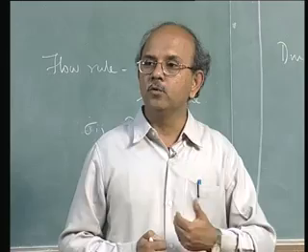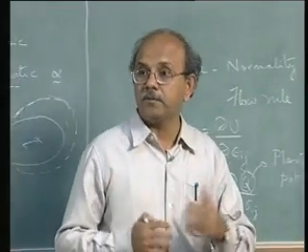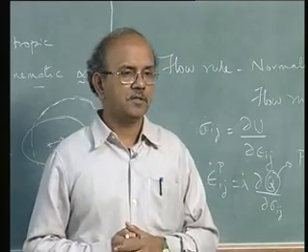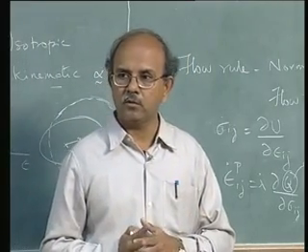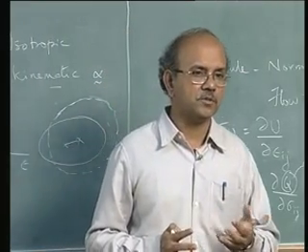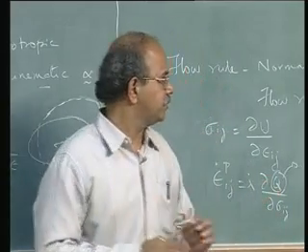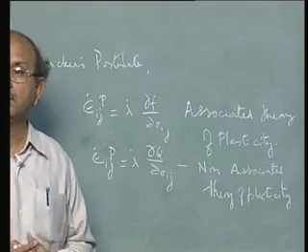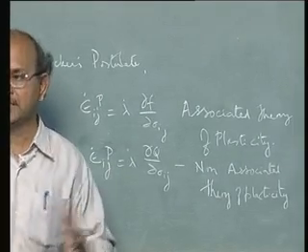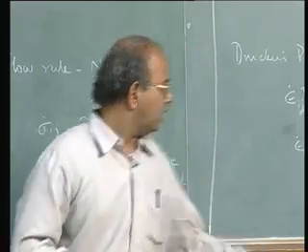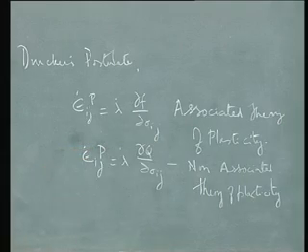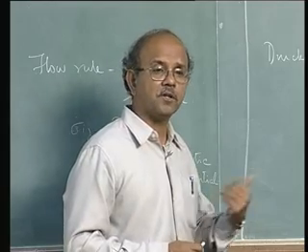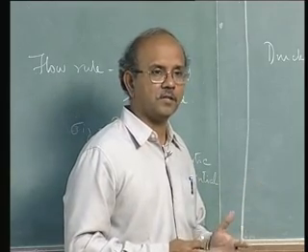But when you want to model the plastic behavior and determine numerically the forming limit diagrams, there are still a lot of issues which have to be sorted out. It's still in the research stage, and some of these issues can be looked at from a non-associative theory of plasticity as well. In other words, though I make a general statement that metals follow associative theory of plasticity, there are situations where the same metals may also be modeled with non-associative theory of plasticity.